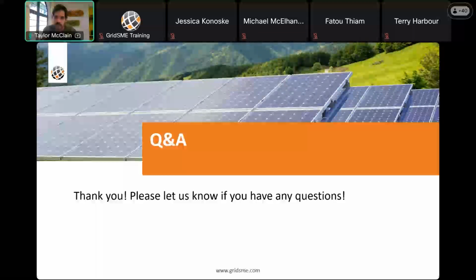During this period of time, that's where you prepare, submit and update your dynamic model. And then as soon as the cluster engagement window closes and they start kicking off the studies, it's very likely that they're going to start with the steady state analysis first. But regardless of what it's called, the system impact study, the phase 1 study, during this initial study period is the first time that they're going to test your dynamic model.